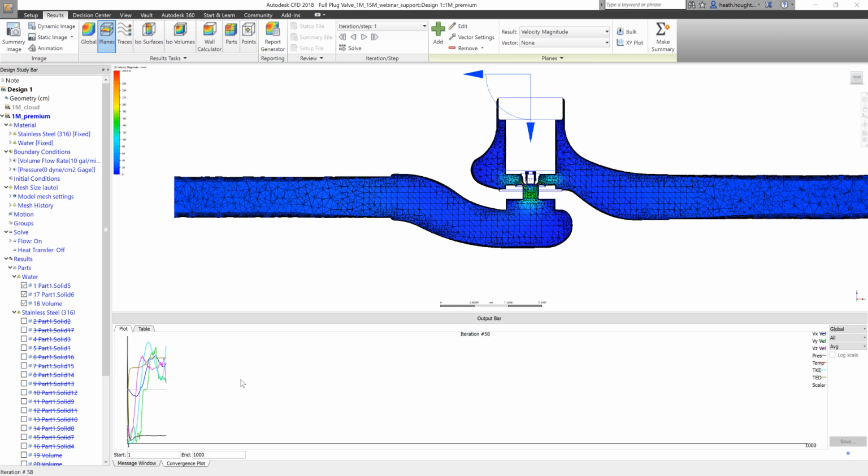What that means is that all the cores really have to sit on the same hardware. You can't connect different hardware together and have it solving the same problem. When you have that type of infrastructure, there will be a limitation on how many cores you can effectively solve with. What we have seen is the benefits past 8 cores for our current solver. It's so finely tuned for up to 8 cores.